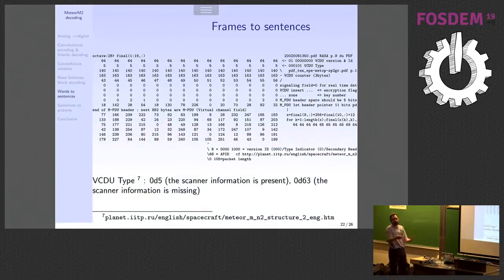which is always the same, that tells you, well, we're doing a good job, there's an ID. Then they tell you there is a counter. Indeed, these 3 bytes, you see that they're increasing one by one, so we're on the right path. And then they tell you, here is a header. This is the address of the first payload, because the difficulty is that you've got the data packet and then you've got the payload packet, and there's no reason for the data packet to be synchronized on payload packets. So you might have payload lying over multiple data packets. This is the address at which the first payload packet starts, and so on. I will not give the details, but that's just a matter of following the protocol. So once you get the bytes, it's really easy.